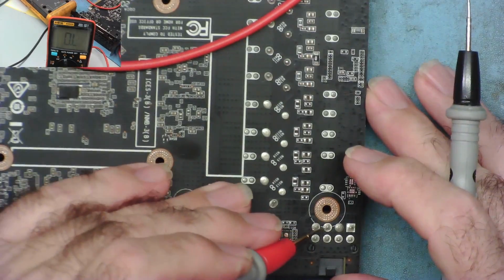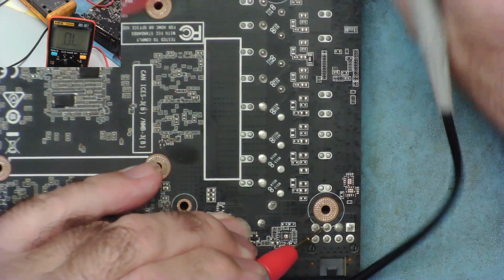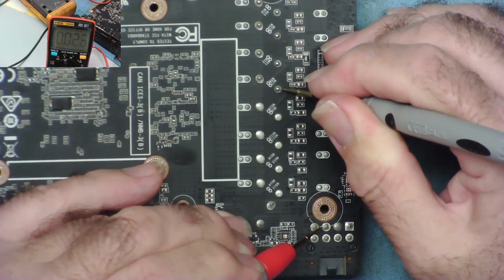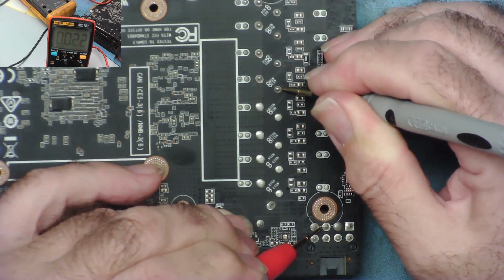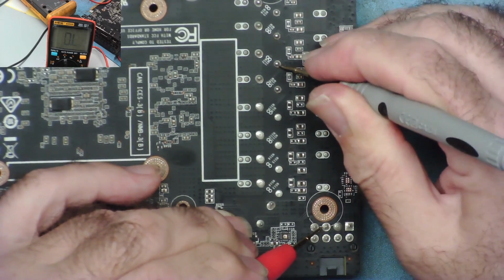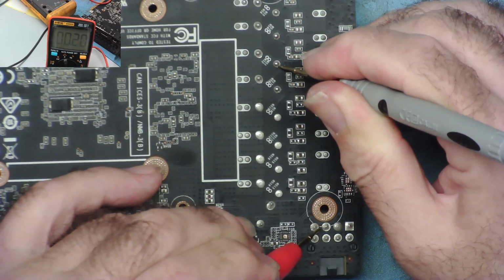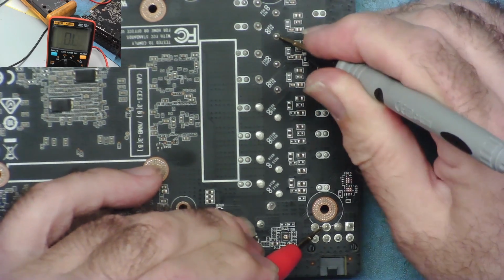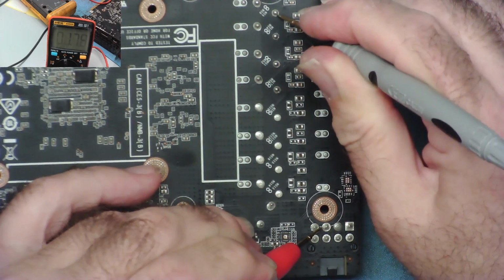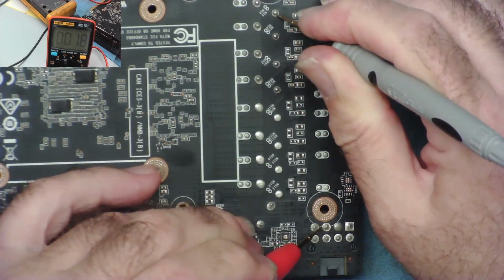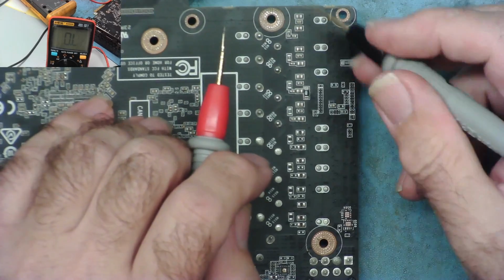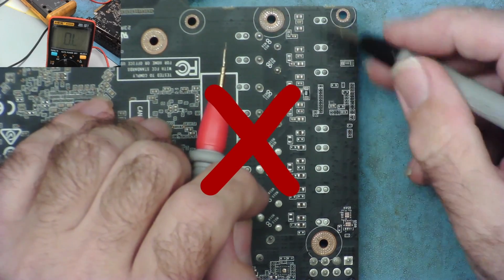So we'll go from the 12 volts coming in here to each of these coils again, and let's see if we can determine which has the short circuit high side MOSFET. So that's reading 0.021, 1920. Basically the same as the leads shorted together. That's reading the same. That's reading the same. That's reading the same. So even with a multimeter that reads to a 100th of an ohm, we cannot determine which high side MOSFET is short circuit.